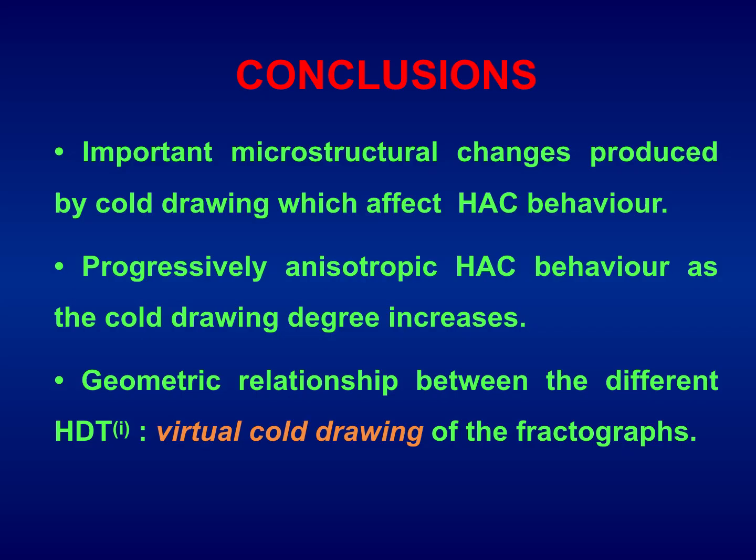First, important microstructural changes produced by cold drawing which affect hydrogen-assisted cracking behavior. Second, progressively anisotropic hydrogen-assisted cracking behavior as the cold drawing degree increases. And finally, there is a geometric relationship between the different HDTs, the different hydrogen damage topographies for different levels of cold drawing, as a sort of virtual cold drawing of the fractographs.